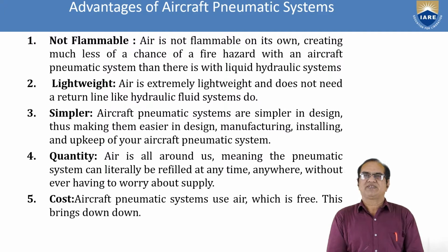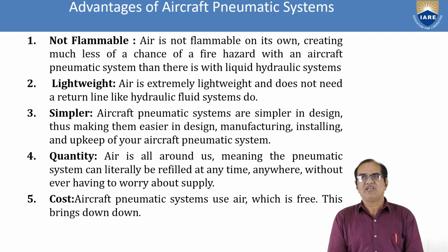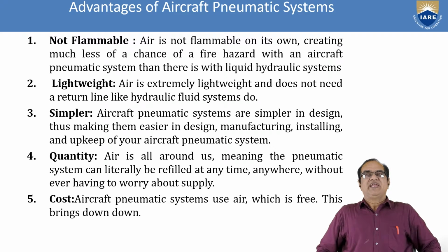It is lightweight. The density of air is very, very low, about 1,000 times less than the fluid or the oil which we are using. The density of that oil may be 880 or 780, something like this. So that much less weight. So air is extremely lightweight and does not need a return line like hydraulic fluid systems do. In hydraulic systems, we need the return line also, so its weight is increased. It is also very simple.